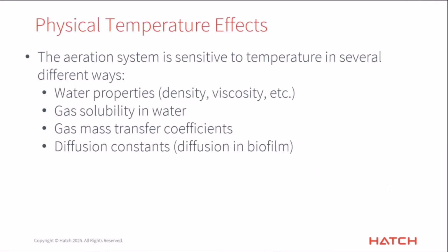All right, so the physical temperature effects, and what I mean by that is the not biological part, the part that's related to the physical components of the system, the mechanical parts and various other things, the mass transfer and so on. The one main one, really quite the most significant part of it, is the aeration system. That is probably the most important when it comes to thinking about how things are affected by the temperature.